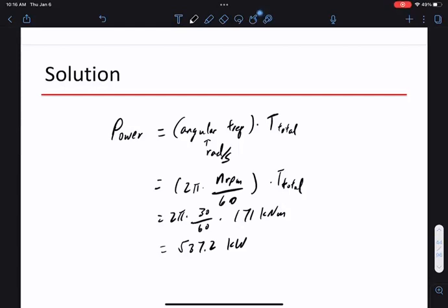But another thing to think of is why not 2 blades? Right? If it's too heavy, 3 blades is also heavy. Is it worthwhile to build 2 blades, maybe a bit larger? You know, power is proportional to area, right? So area matters. How much power can you extract? Area matters. The center of gravity matters. The distance from the hub center of gravity matters.